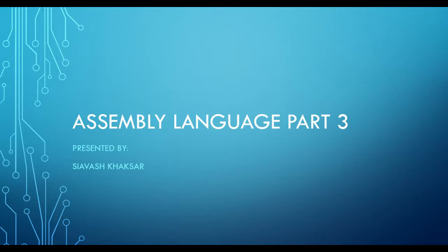I just want to comment on the template that's given to you for the blinking LEDs for the labs. You deal with a few of the registers: P out, P in. P in is basically for checking. I think you've covered that in your lab 1 and lab 2 as well, the C programming part. All the labs are fundamentally about just these few registers. The PX out, whatever value that you put in, you will blink the LED.